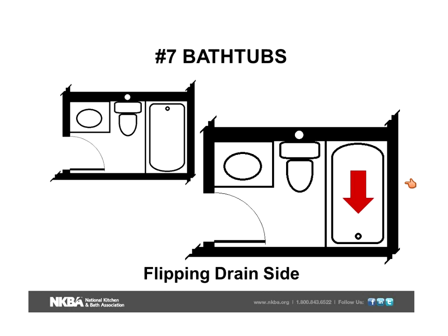Now, those of you that have had a plumbing class with me, you've already figured out that that wall is thicker than this wall. You know that this is a wet wall. And we see that it is wider so that we can get that 3 or 4 inch vent stack in that stud wall using 2x6s.